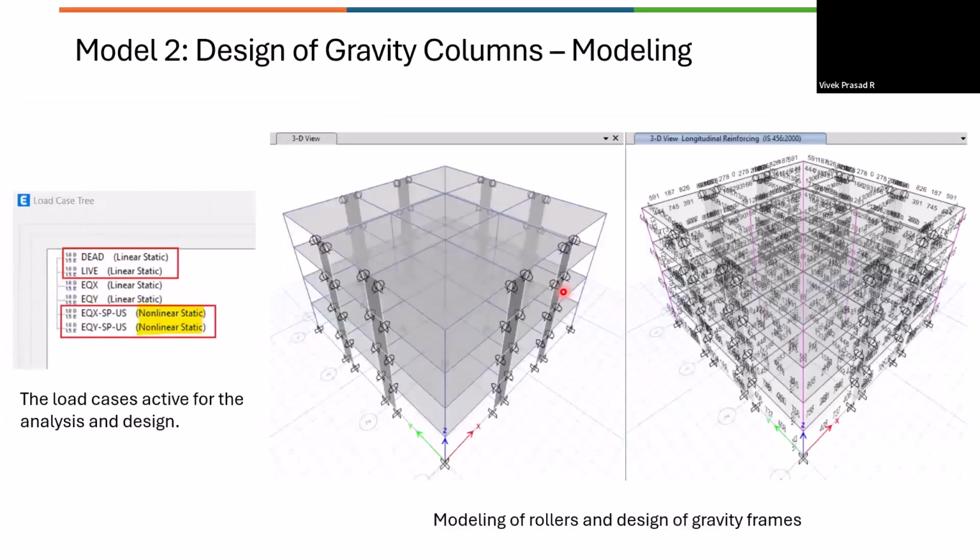For that, we need to remove the participation of the lateral force resisting system. So in this example, I replace the actual property by none and then put roller supports to give the vertical support. But this is about the displacement. You can see the results here.